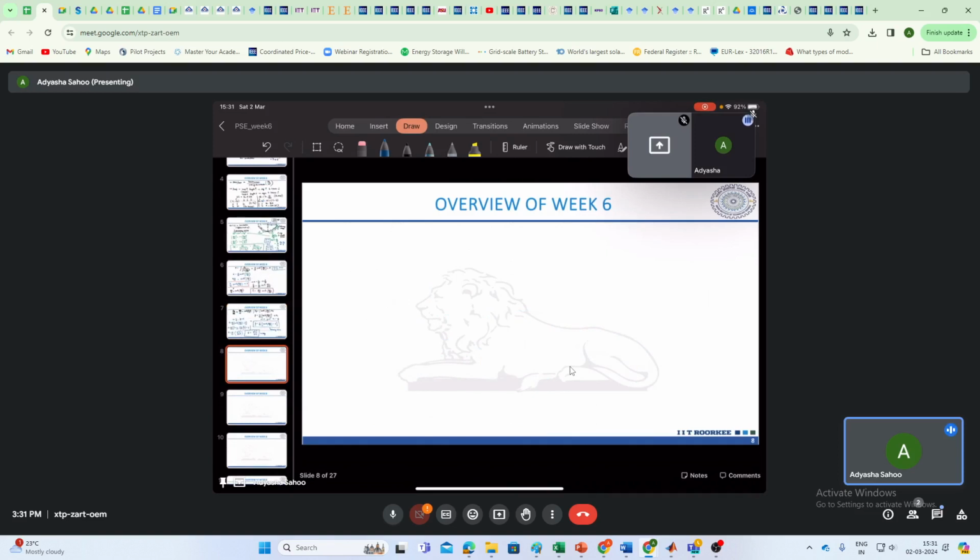Now we'll see when it is suspended from a tower, so we'll see those parameters. Basically this is your catenary curve, and let's say this distance is capital L, the span length, and this is L by 2, half the length of the conductor. So this is midway, L by 2.